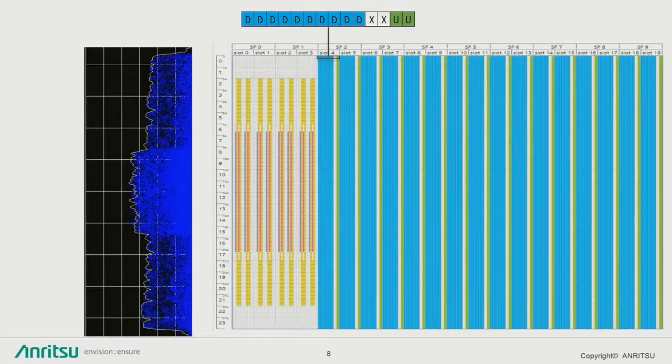This is frequency, okay, so this is like a spectrum. How many of you have used a spectrum analyzer before? Okay, this is your RF portion, so this is time, and this is RF. I was going to rotate it, but it got a little bit more complicated, so this hopefully will be okay. And you'll notice that you've got a little bit more signal here, and we'll cover that in a minute. But all of this is your user data. And this piece of information will repeat every 10 to 20 milliseconds. And we know that this is 1 millisecond. So if you look at slot 0 all the way to slot 19, that gives you your 20 milliseconds. Okay? So this is how the 5G format is sent over the air.